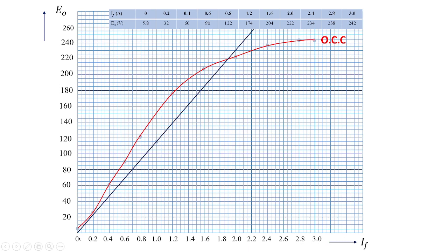So with this I have drawn the shunt field resistance line, and this is cutting approximately at point A, and that point here is the value of no load voltage which is going to get excited at 220 volts. So this is our first intention, that is no load voltage to which it is getting excited, that is 220 volts. Now a tangent is drawn to this OCC curve, and slope is identified with the points P, R, and Q like this.